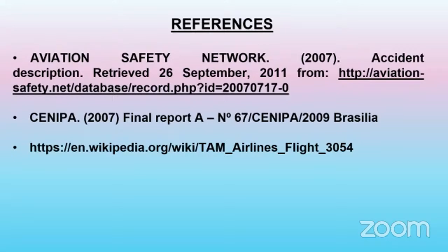This is Valodi, I would like to answer. Go ahead. Owing to the aircraft limitation, wherein one of the thrust reversers was unserviceable, and also knowing the present condition of the airport because of the local conditions of rain, there was a problem. So the pilot decided he would go for a manual approach and use the entire runway. In order to do that, he decided that if he could touch down a bit early, that would give him some leeway while landing. The old landing procedure prescribed by the airlines was much more effective, as during the landing it would have saved him about 50 to 60 meters of the runway.